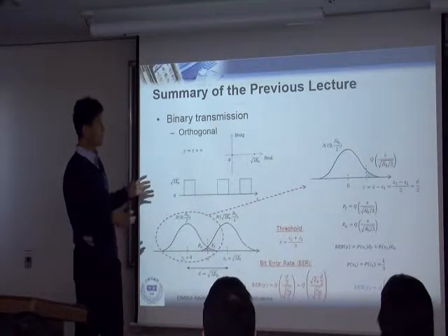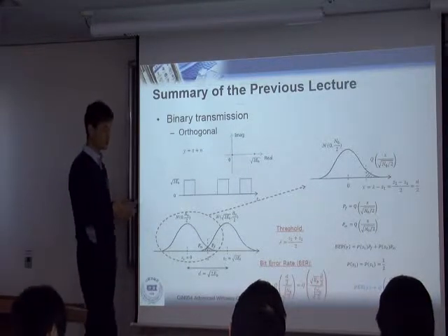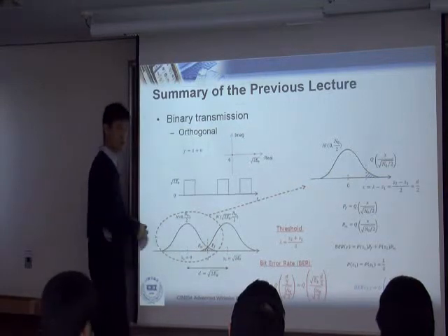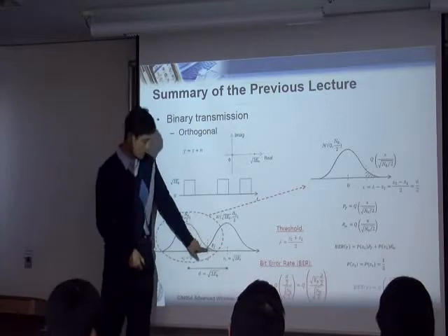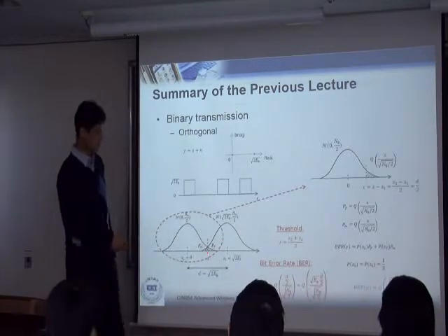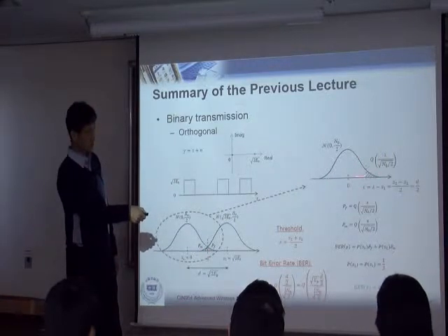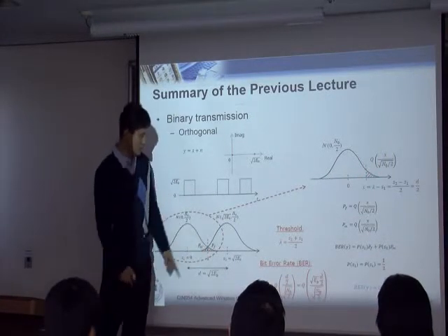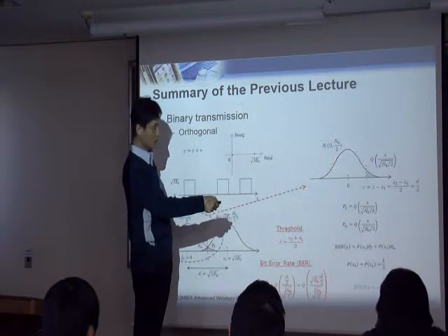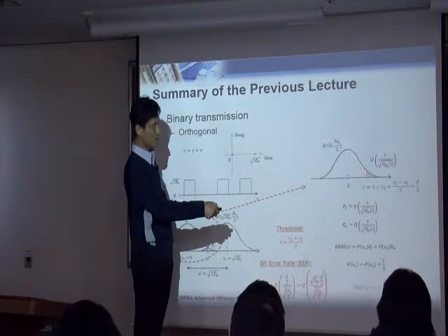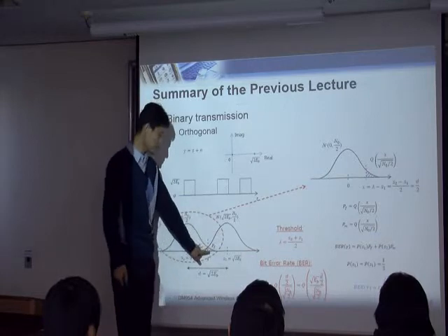So typically when you propose or design a system, your goal is to reduce the sum of these. This can be modeled. In fact, look at F1. Just look at the blue shaded region. This region can be calculated by the Q function. Since we are using the Gaussian distribution, this area can be simply calculated by the Q function.